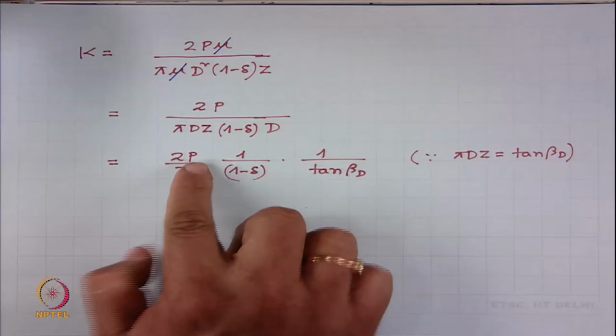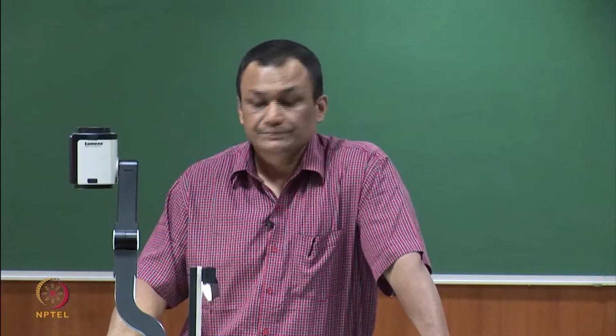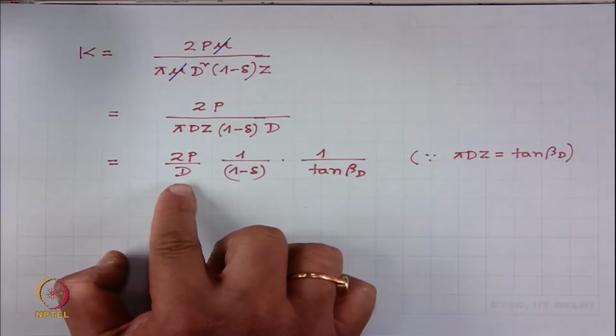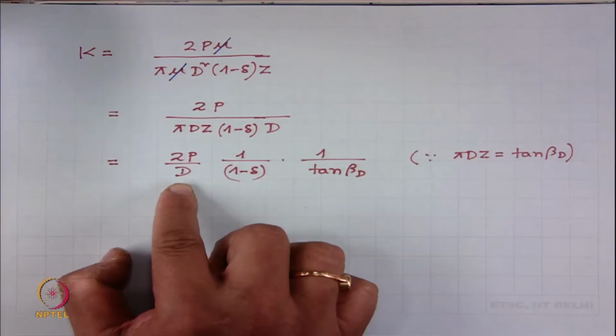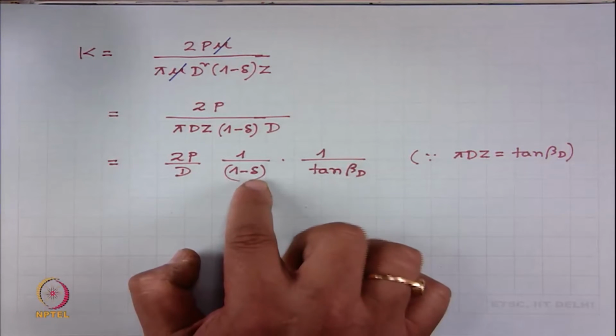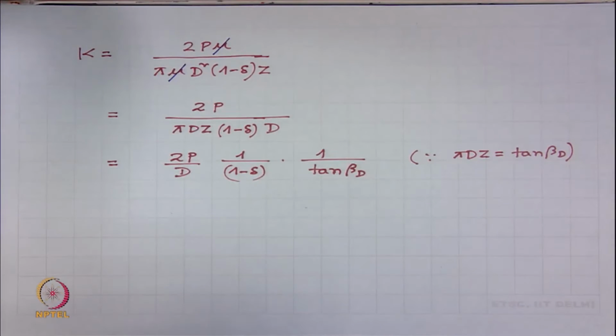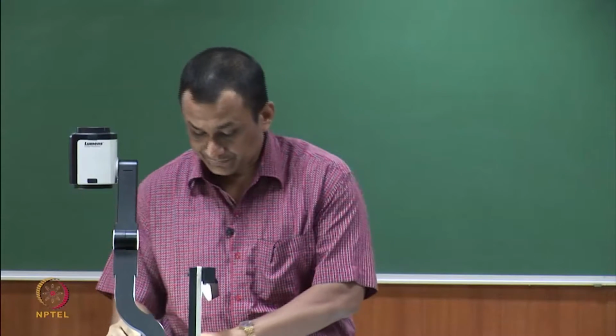Period of migration has a dimension of length, millimeter. Yarn diameter also has length dimension, millimeter. So, these two length dimensions cancel out. Yarn retraction is dimensionless, pi d Z, the twist intensity, is also dimensionless. So, K is a dimensionless quantity.